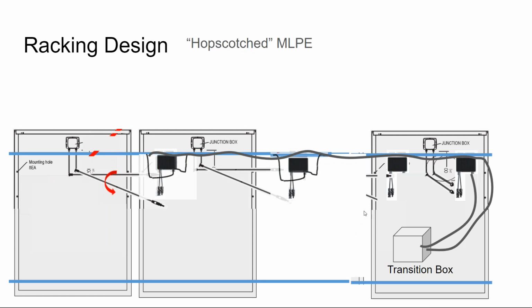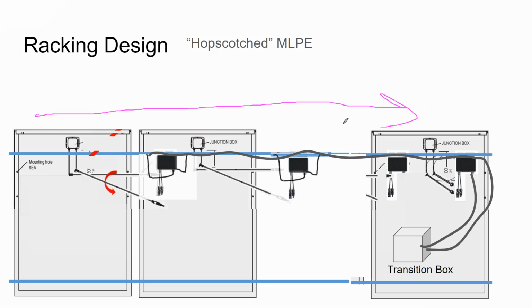Even though there are now better safety provisions built into the systems that didn't exist back in 2008, that copper inside aluminum conduit burnt down a few buildings for commercial projects because the conduit got long enough without any expansion joints, and so the systems would literally pull apart, and then the frayed conduit would start biting into the solar cable, combined with a lack of arc fault protections and or ground whatever.